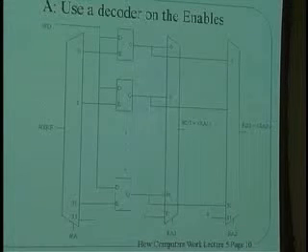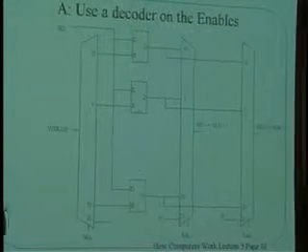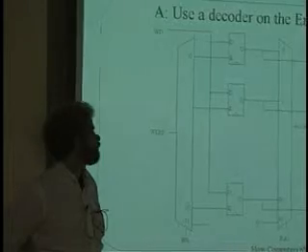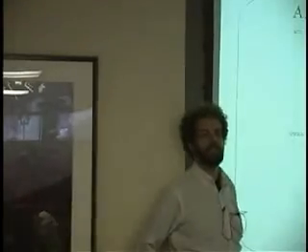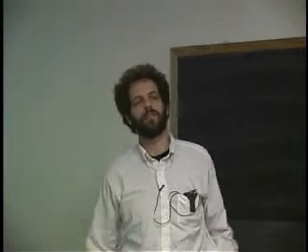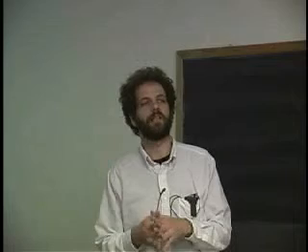So if you go through the different opcodes that we went through, you'll see that in some of the cases, WRF was set to 0. And in those cases, the idea is that the register file is told, don't write. Okay. How is that different from having the word be 1? It's exactly the same. But sometimes we're using the bits for register C for some other reason. And so I think that you'll find when you look at the code that there are some of those cases where we want WRF to, in fact, be 0 because we're using those bits for some other thing.